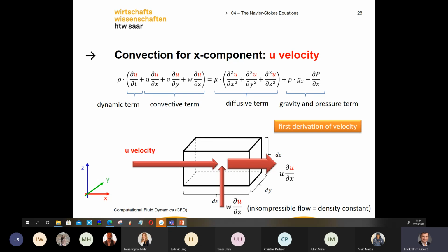So here again is the same description of convection of the u velocity. You have a big part in u direction, but you add something from w direction. You have to add a u component from w. It comes from the cell below, and so your derivation can also be bigger than the momentum that entered here.